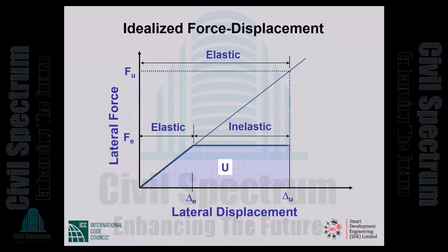The inelastic displacement cannot be such that our structure will collapse on us. So we should not set the design strength level so low that the resulting inelastic displacement exceeds what we call the inelastic deformation capacity of the structure, the capacity of the structure to withstand inelastic displacements while still carrying full factored gravity loads.